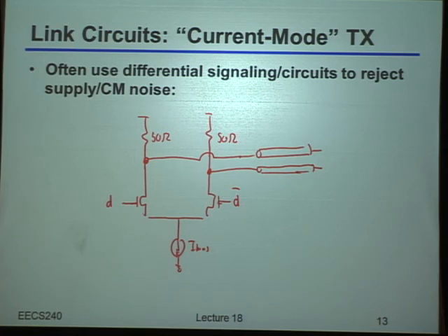So the penalty that you're really paying here is that if you really want this thing to behave as a current source, and I'll ask you guys, if I really want this, for example, tail transistor down here to act like a current source, what does that mean about sort of the lowest voltage I can put across there? What would that typically be? Yeah, something like K times V star.